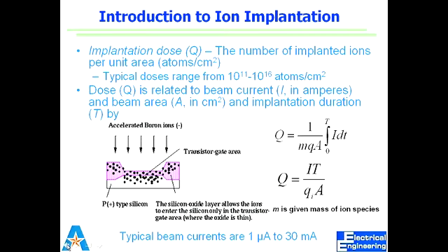You won't have to do that because in low cost what we can do is we can deposit silicon nitride everywhere and pattern nitride. Right? So now once we have patterned the nitride, if I have silicon dioxide, silicon, and a patterned silicon nitride, right? And then I can do oxidation, and this guy is going to just become thick, right? So this is all oxide, and then I can remove silicon nitride. What I'm left with is something like that. Make sense? How can we remove silicon nitride?